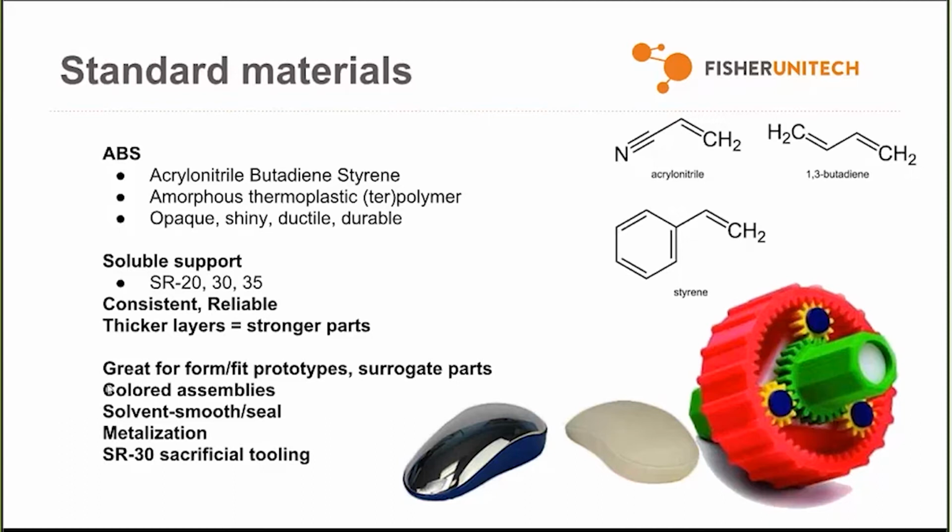I go into a little more depth in my class, but anyway, that fact, thicker layers, stronger parts, wider tool paths, stronger parts, that's true of every material that I'm aware of. But I'm mentioning it here early on because, frankly, not every machine can run other materials than ABS. And so if you've been running ABS, maybe running into problems at 5 thou or 7 thousandths of an inch, I want to explain that so that you can get the most out of your machine.